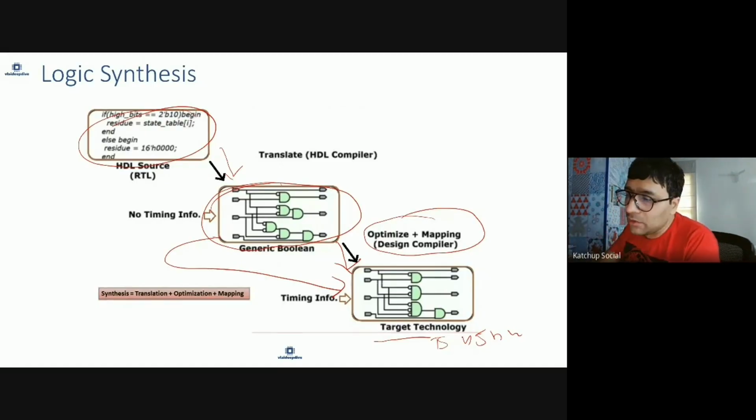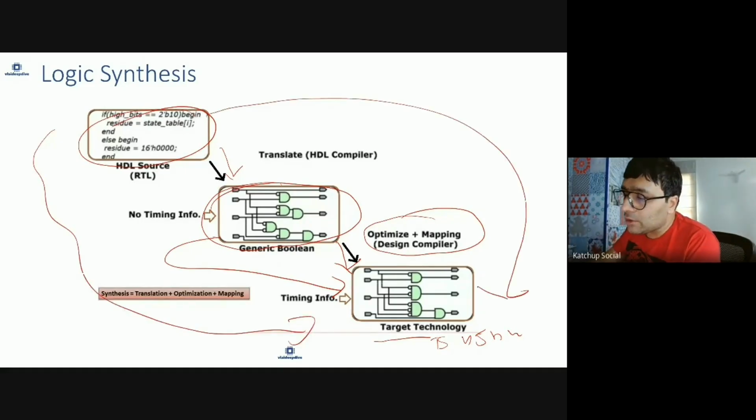This all happens during synthesis. You start with RTL, and the output is your AND OR gate based logic. This is also known as the netlist, which is usually in Verilog format, but if you are running FPGAs, Xilinx may have a specific format. It is mapped to a specific technology, in the case of FPGA, the specific board which supports it.